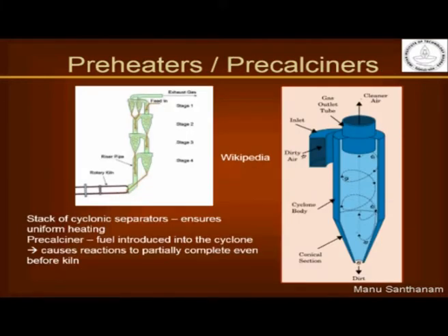Okay. So once this material has been blended, in most cases we have what is known as a preheater tower, through which the blended raw material, that means the clay and limestone which has been pulverized and then mixed together, goes through this stack of towers known as a preheater tower. Now this preheater tower has several of these stacks. You see here the feed that is coming in at one end goes through several of these cyclonic stacks.